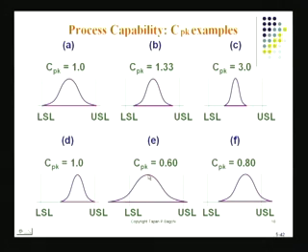If there is a displacement of x double bar from the target value there, unfortunately, you cannot see them because those have been erased from this picture, but x double bar stands here and your target value stands there. There is a difference between those two. So this process lacks accuracy, and look at the tail, it has fallen out. Same thing with this. Even if this process is narrower, tighter than the process here, still CPK is poor.